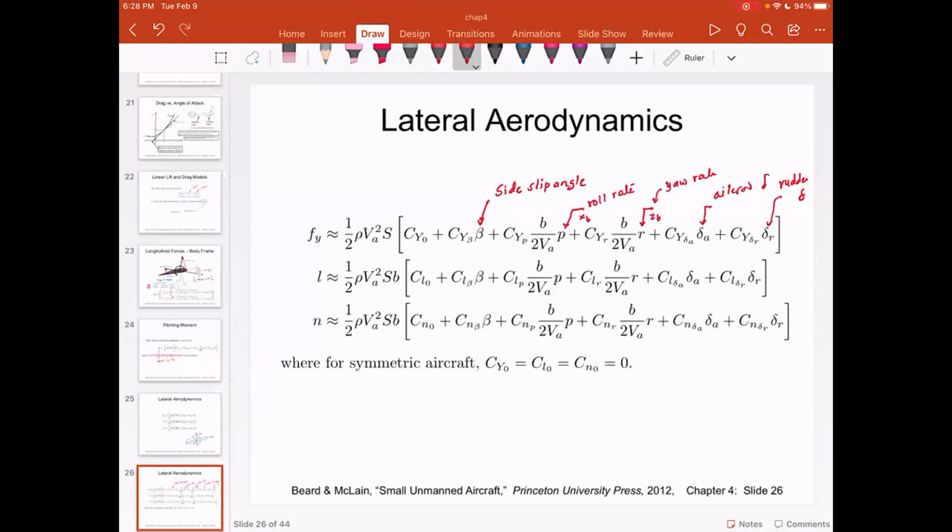So what is happening here is the first quantity, which is the dynamic pressure, is remaining the same, 1/2 rho VA square. Dynamic pressure gets multiplied by S, which is the area, that gives you the force in newtons.